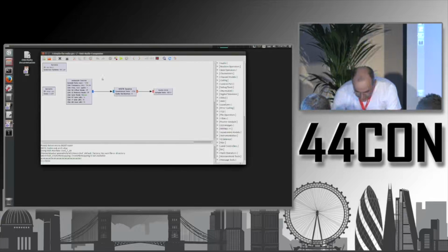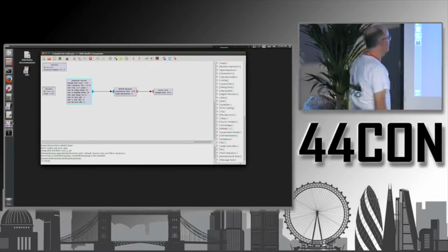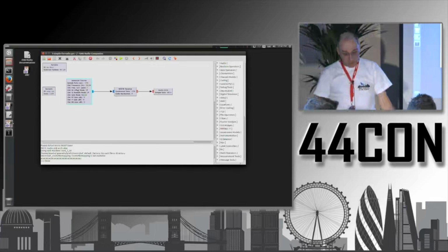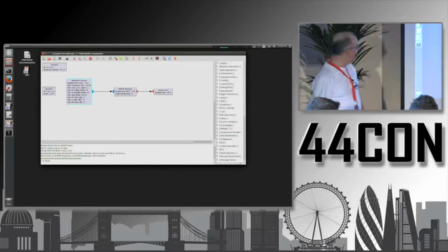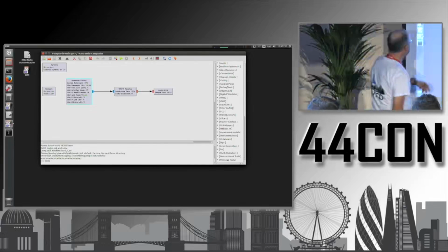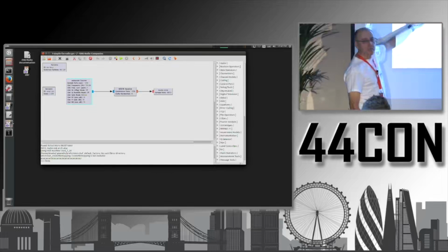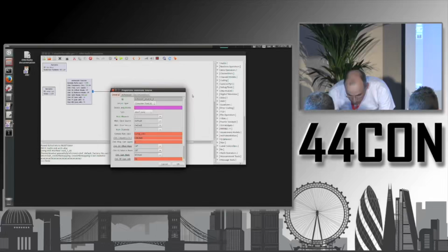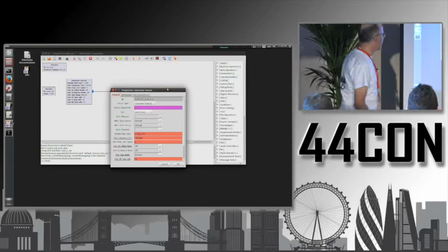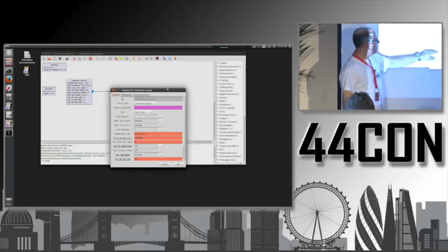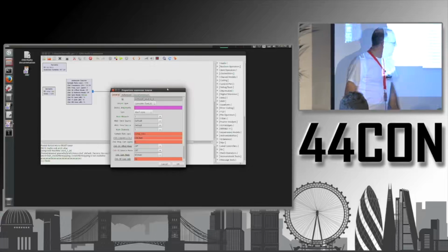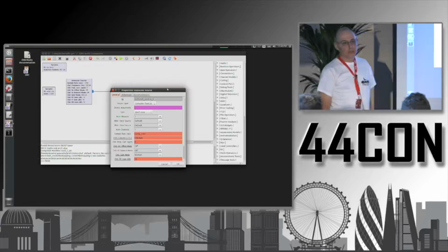I had good reception of a local radio here, 89.1, but here in this room not. If you want to try it out, here on the Osmocom source, double click this block, and here you can see a frequency in hertz. 1,600,000, that's exponential notation.